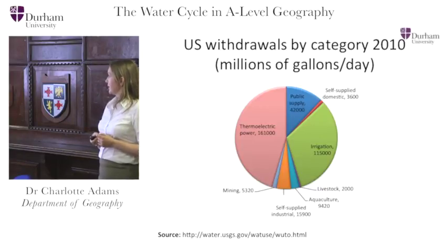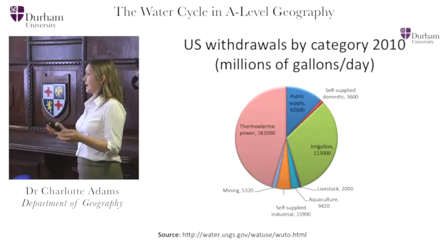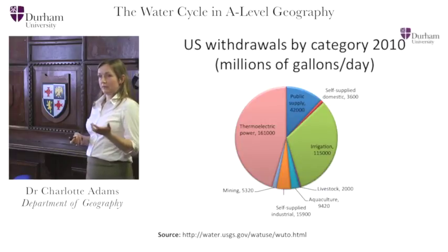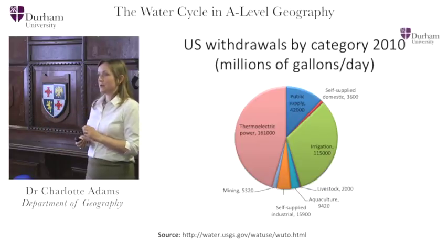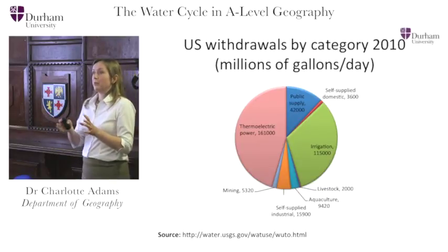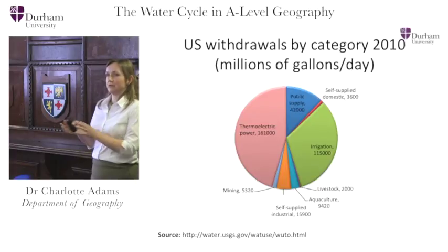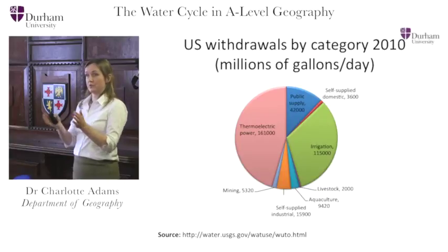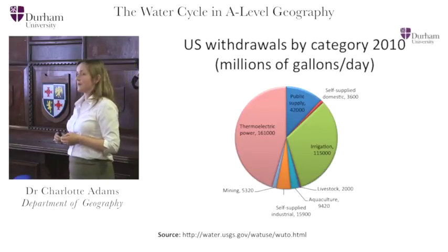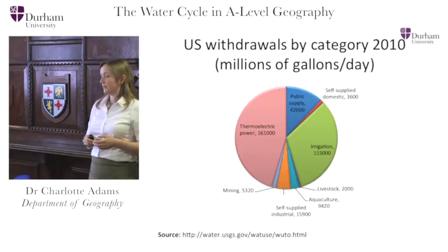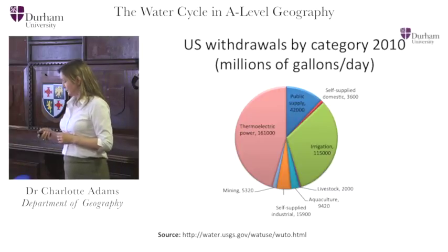If you've got power plants that are located coastally, it's not so bad because you can cool using seawater. Inland, you're either taking from rivers or you're having big ponds at the power plant to cool using that. Or you're putting in big air cooling towers, but with air cooling you need it quite big to deliver the same amount of cooling that you would get from water, because water is such a great medium for transferring heat. So there's something to think about there in terms of how future power plants are designed. They should be designed with future water shortages in mind.